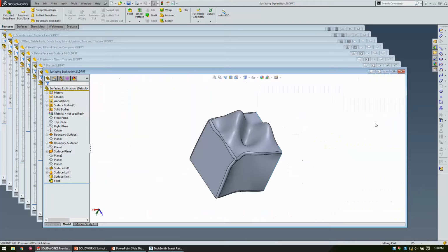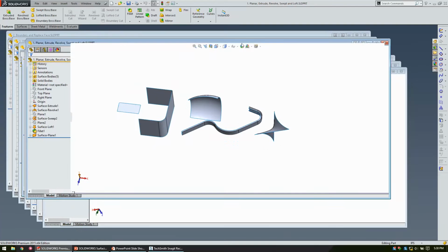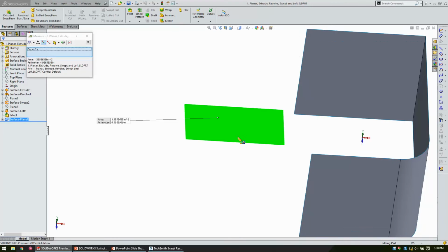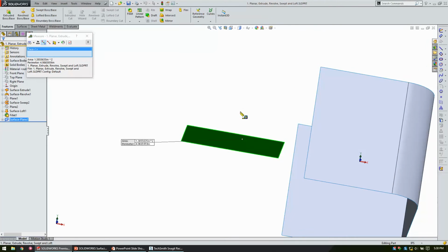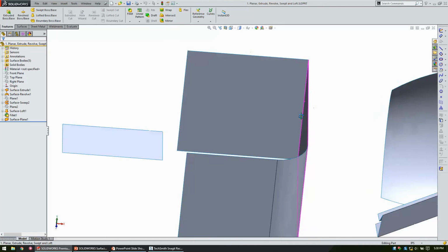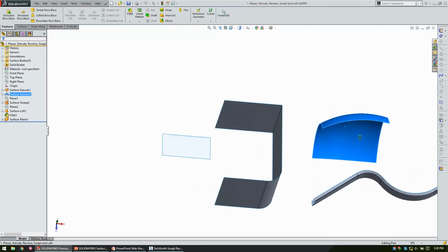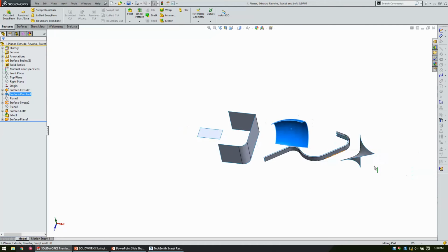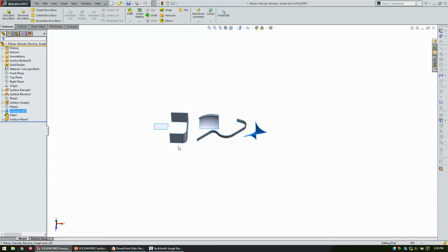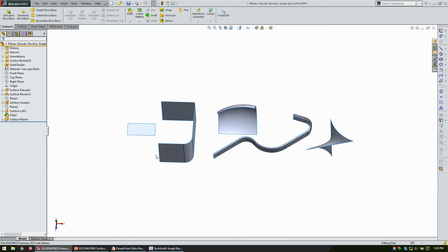And we'll jump between PowerPoint and SOLIDWORKS here quite a bit. But it's like this. So here is, if I try to measure this thickness, notice that I'm selecting and deselecting this on either side. It's a zero thickness body that has no depth, no Z depth to it. And of course you can do this in multiple configurations. You get the typical extrudes, sweeps, revolves, lofts, and you can kind of get contorted surfaces, which is kind of fun. But that's what surfacing is. It's zero thickness. It's just a shell of something. If you do enough of it, you can thicken it or enclose a solid volume or whatever it may be.